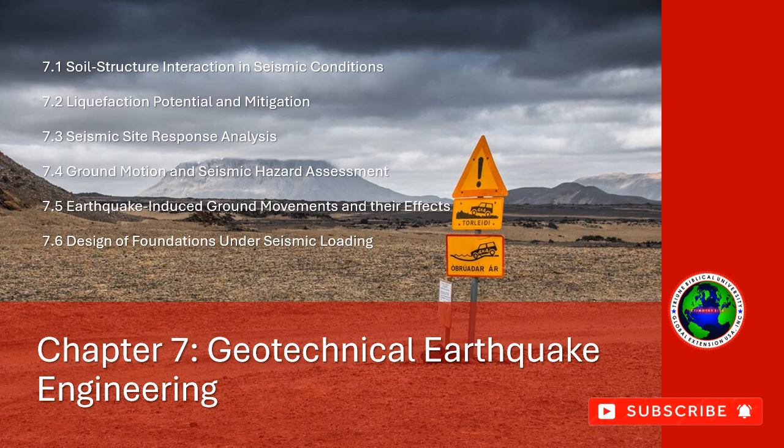Key steps in 1D site response analysis. Input ground motion: the seismic motion at the bedrock or bottom of the soil profile is used as the input motion. Soil layers and properties: the soil profile, including the thickness, stiffness, shear modulus, damping, and density of each layer, is defined. The material properties of each layer are essential in determining the seismic wave propagation.